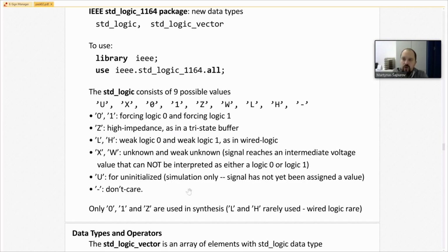The input has a very high impedance. This means that it can read the parameters of a circuit, but doesn't change it at all. For example, if we're talking about field effect transistors at an output, which are mostly employed, usually we'll have the drain of a field effect transistor connected to an output directly.